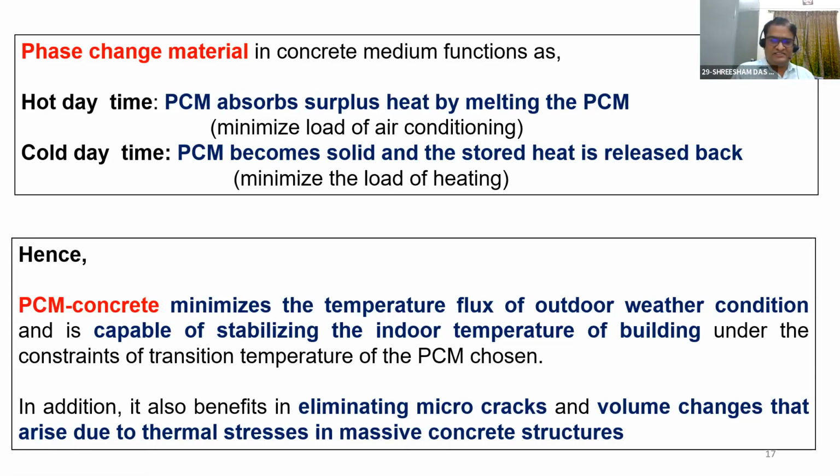Similarly, in cold conditions, for example at night, if the diurnal variation is too much, the PCM becomes solid and the stored heat is released back. So in cold weather you need not switch on the heater, because it will not allow the outside cooling into the building, as the PCM is solidified.